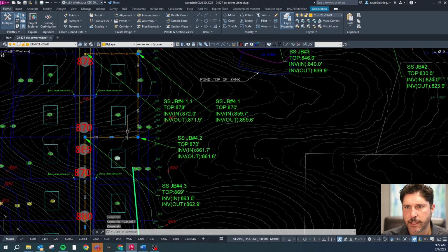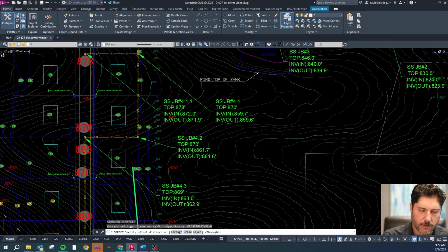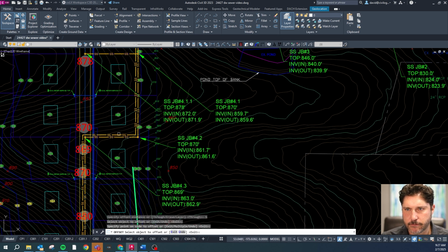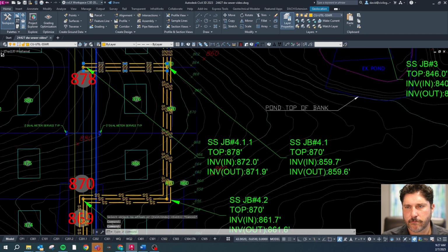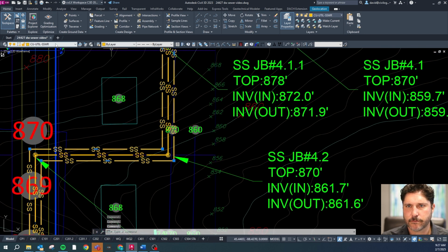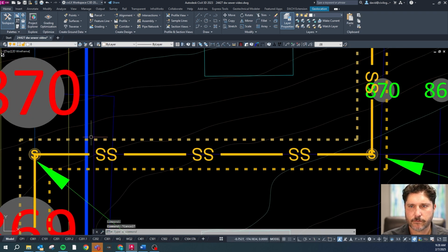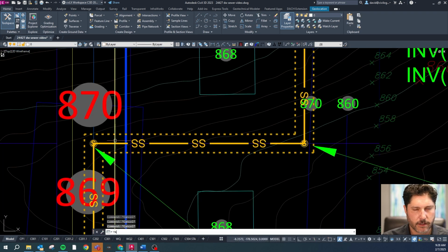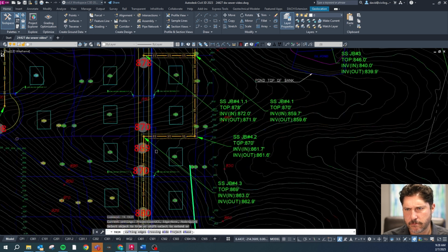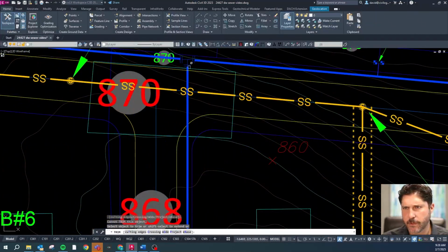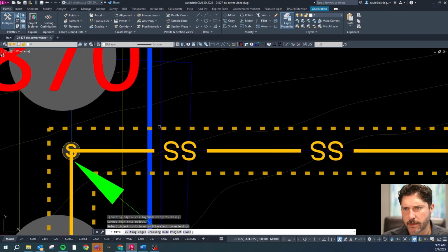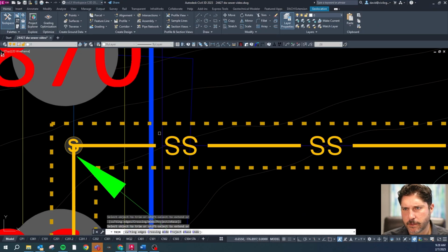So that's generally it. We could throw an easement on here. So let's do that real quick. We'll offset 5 feet on either side. Turn these into easements. And that should be a proposed easement. So let's go up here to CA easement. Once we get to the right-of-way line, it doesn't need to exist anymore. What are those 2 lines? Oh, that's the water line. Okay, so this is the right-of-way line right here. So let's trim that.